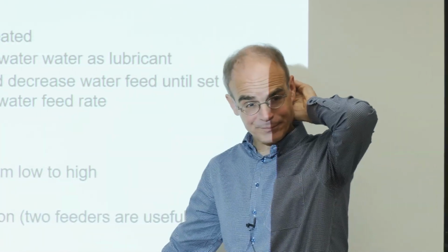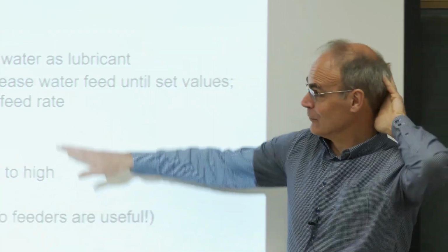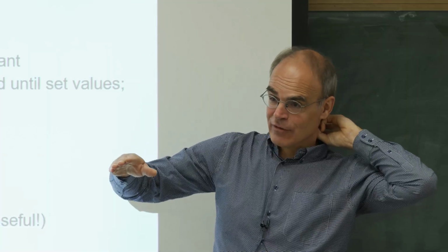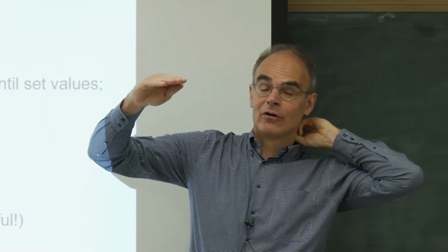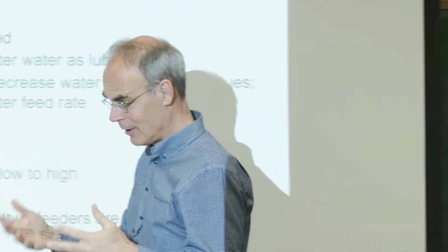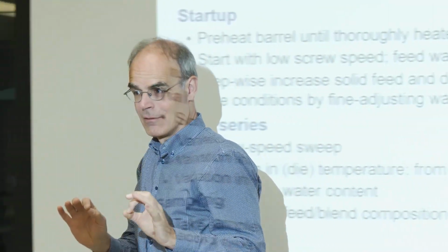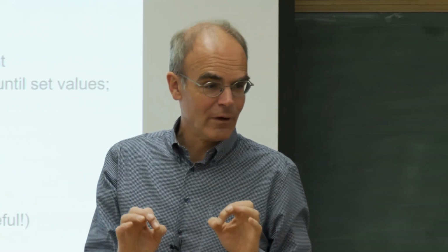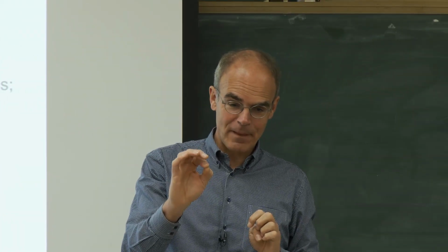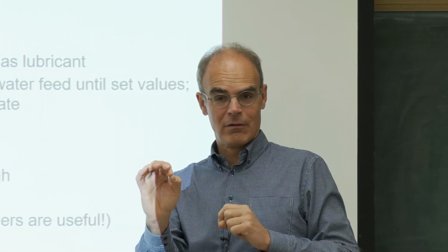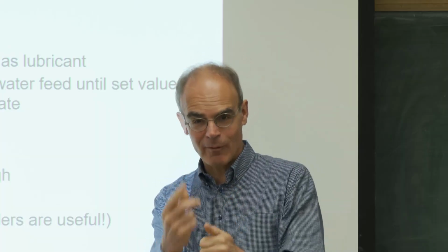Typically, what I do is the reverse of what you do here. So gradually decrease your solid feed, increase your water feed. So you're going to make it more and more liquidy. There is a limit to it. The thing is, upon starting up, you're increasing the viscosity because you increase solid feed and decrease the water feed. So what happens with the viscosity? Goes up. Yes, I see someone pointing up a finger.